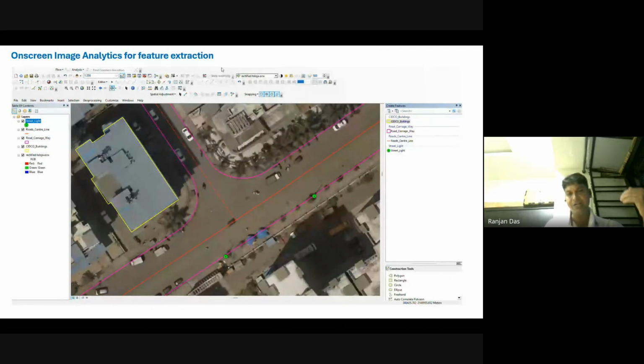Then we have added the geospatial locations or addresses by the georeferencing process. Thirdly, we have captured this data, feature extracted it from raster and converted it to vector. You can say I have converted it into DWG, my CAD data is there, no issue. We are converting into a drawing file. When we have converted that file, you will be able to attach your attributes to that data, because raster cannot contain attributes. That is the main reason behind it.